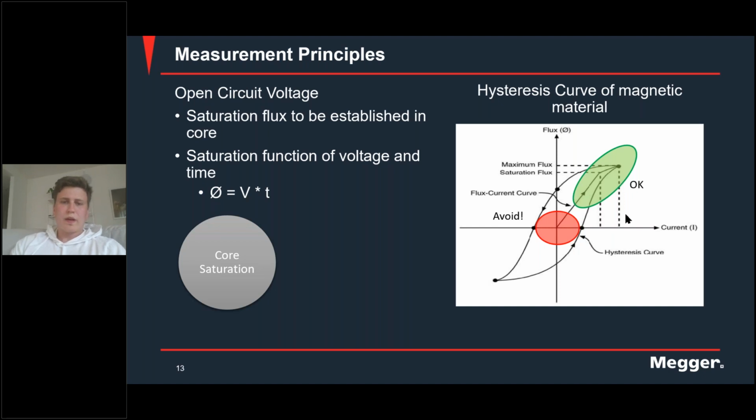That's all. Yeah, and of course you have to go below the saturation point, else your current is not going to. So you have to saturate it up until that point, and then depending on how much more you saturate it will influence the inductance. There's also another aspect, depending on if you have a 3 or 5-legged transformer, because sometimes if you have a 3-legged transformer core, it doesn't really matter if the other legs are magnetized or not, because once you magnetize one, the other will appear magnetized.